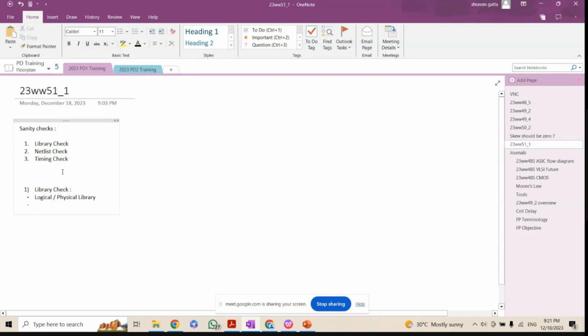Okay, so this is the netlist checker. We learned that the netlist should not have outputs tied to the ground, no floating inputs, no multi-driven nets, and no combinational feedback loops. They shouldn't be present in our netlist. All good, but how do we check, right?